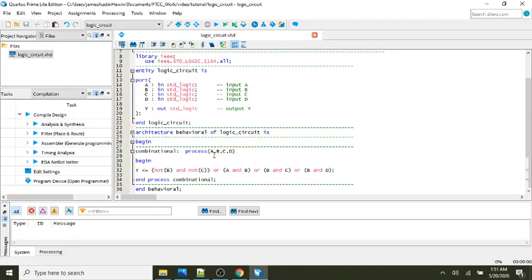And that's it. I put these signals, these A, B, C, D, inside what's called the sensitivity list of the process. And all that really means is that when the simulation's running, whenever any of these 4 variables change value, then this process will be executed. So it'll update Y, which is what we want. Anytime your inputs change, you want to update your output. So that's exactly what we want. And that's it. That's all there is to this simple example here.